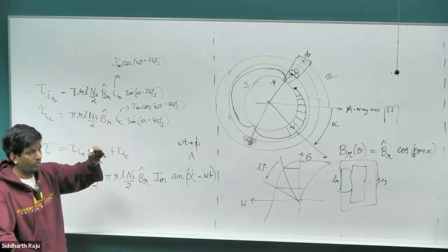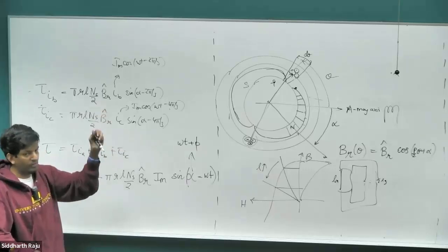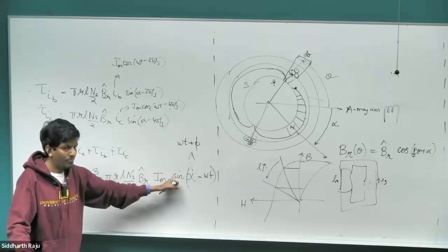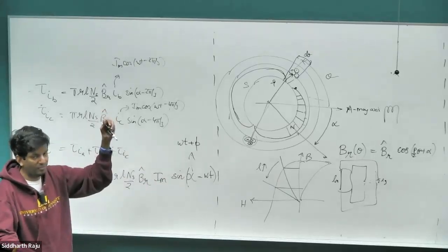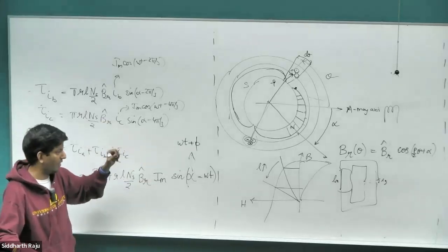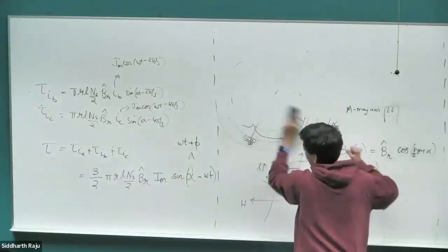So if the rotor rotates at the same speed as your stator magnetic field, the air gap magnetic field that we created is rotating, then you can produce a net torque in the system. But if it slows down, and you cannot recover the speed back up again at steady state, then the system will come to a stop and you'll end up burning the winding because there is no back EMF that's created. So let me just take 2 more minutes and with that I'll finish it off.